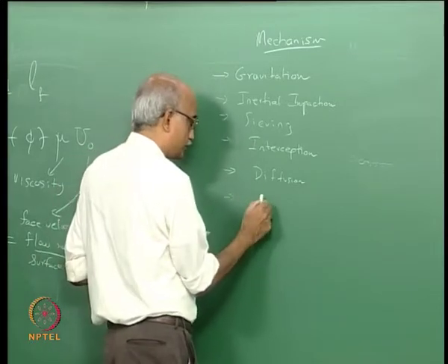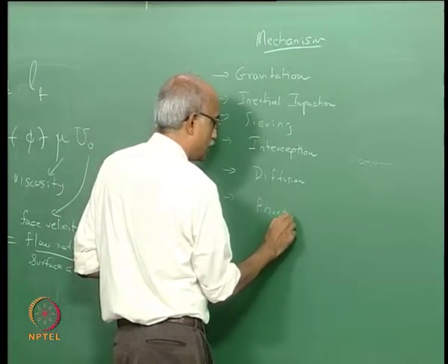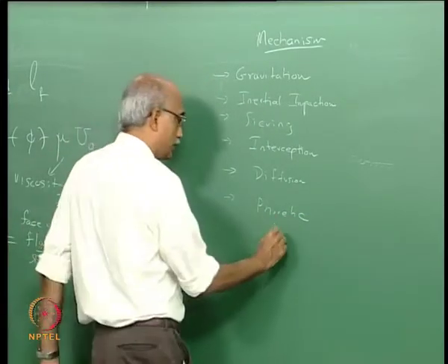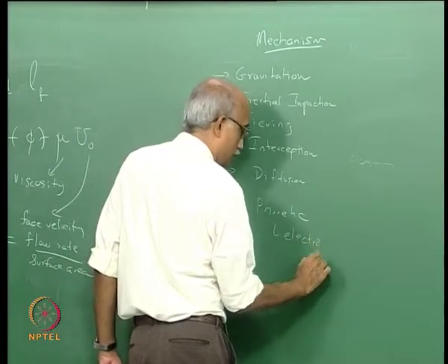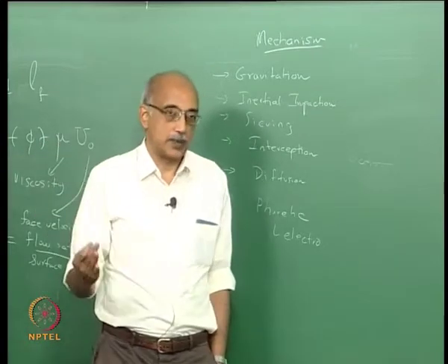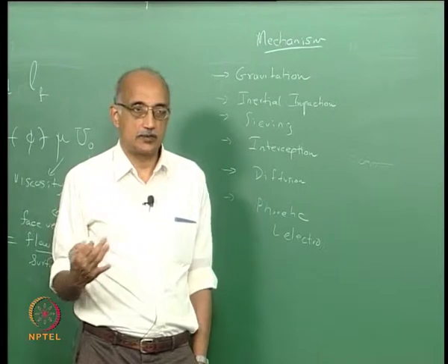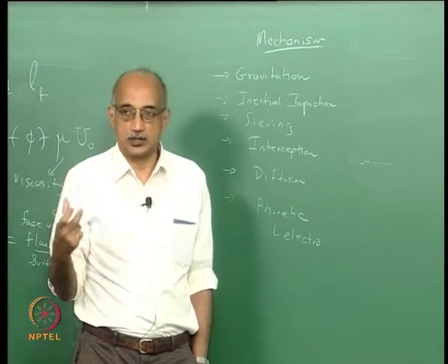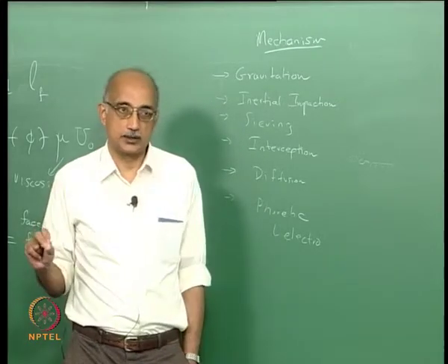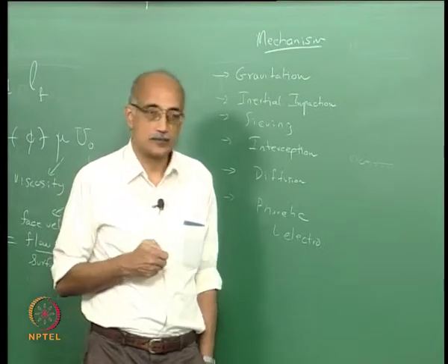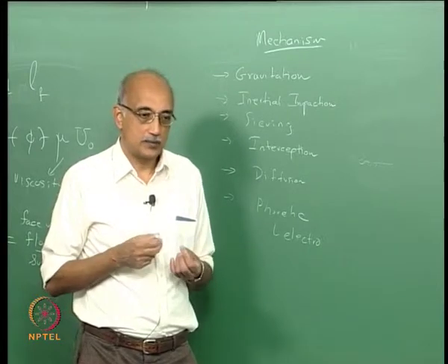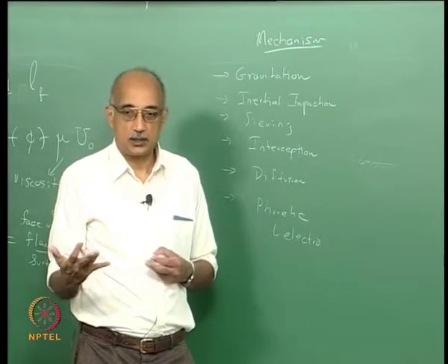Of course, the phoretic forces are also important in collecting particles. For example, you can have electrophoretic filters, and the electrostatic filters can be both active and passive. What we mean by an active electrostatic filter is where the filter medium is deliberately charged to a certain charge, and this is particularly useful in removing charged particles of the opposite charge, obviously. Whereas a passive electrostatic filter is simply one that develops a charge on its own.